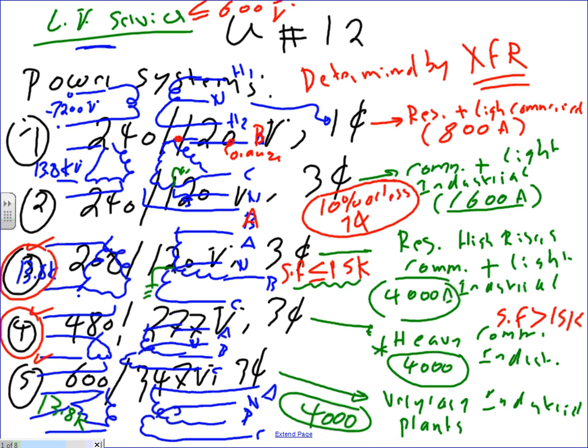So I thought I'd just throw these power systems out, so you guys, as you start designing your building, the first thing you need to understand is what voltage system we are going to be using. The mechanical engineers are going to ask you, we're going to buy a chiller, what voltage do you want to burn these chillers at? So you have to decide the voltage system.